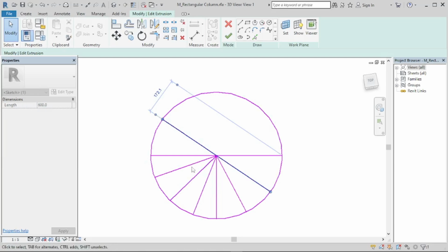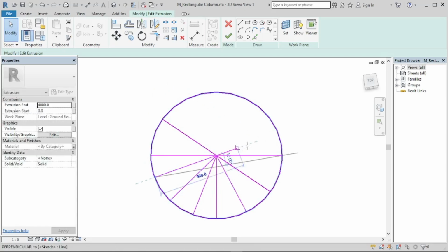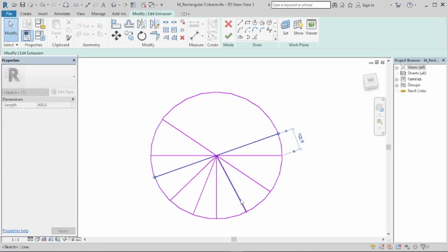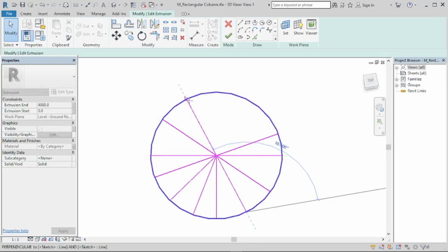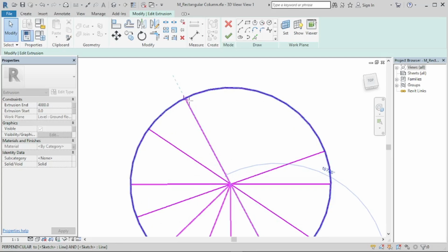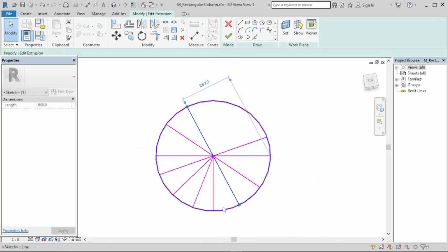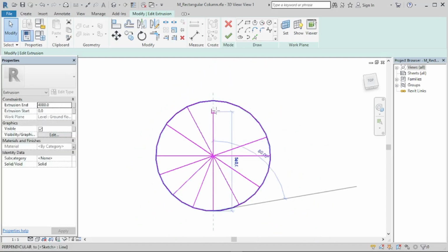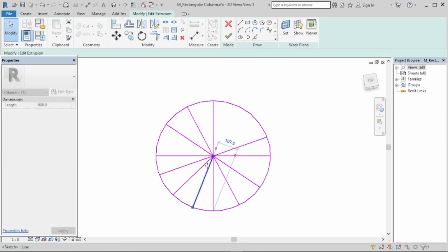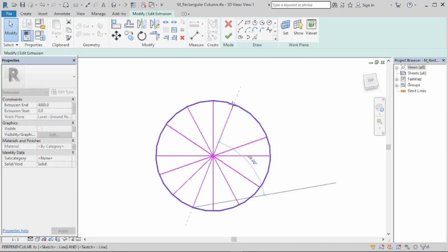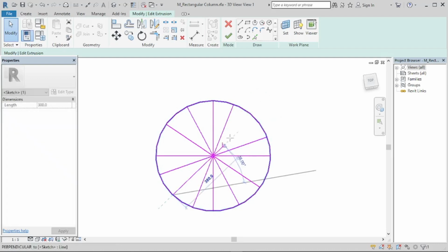to this point, and as you extend it, make sure it snaps, so it doesn't go off its direction, doesn't go off its path. Make sure you see the dash line that extends, and that it shows that it snaps and hasn't gone off its direction. So we want this one also to go up to here, this to go up to here, this to go up to here. Yeah, I think we've completed that.